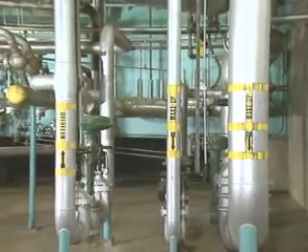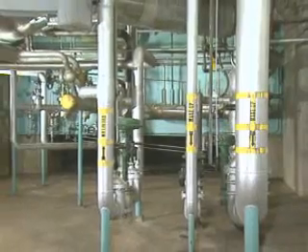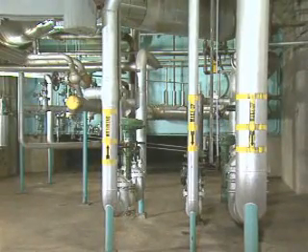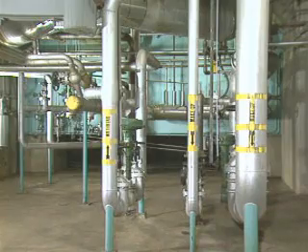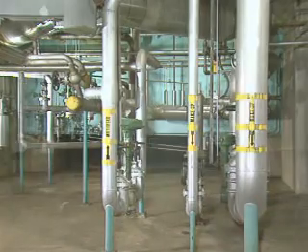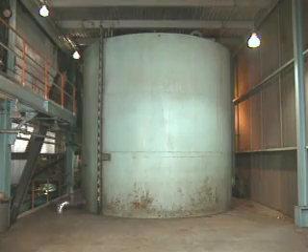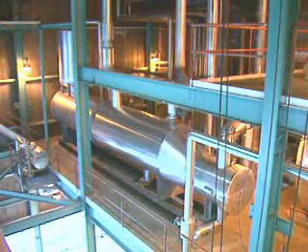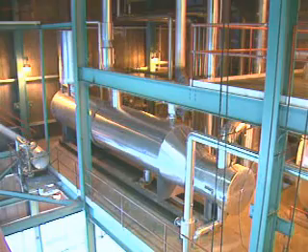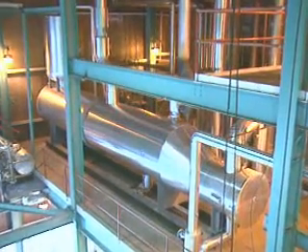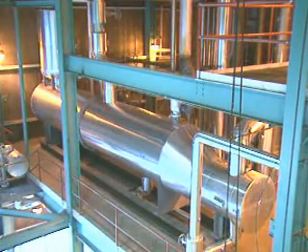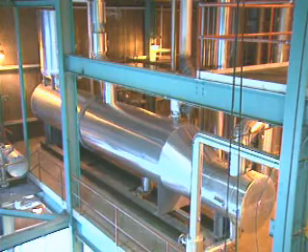This system adds pure water to the condensate system to compensate for water losses that may occur due to condensate sampling or to steam or water leaks in the system. The make-up water is stored in a condensate storage tank. Make-up water system designs vary, but most also include purifying equipment such as evaporators and demineralizers.